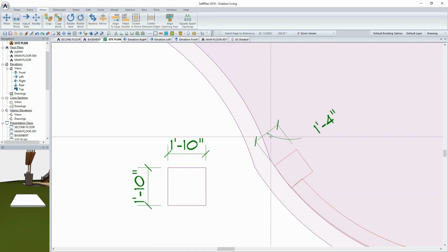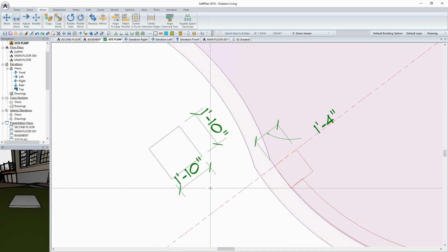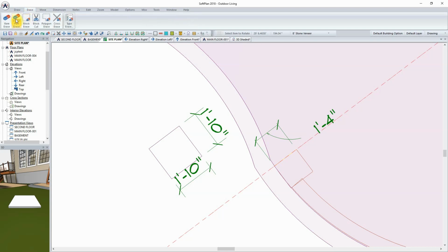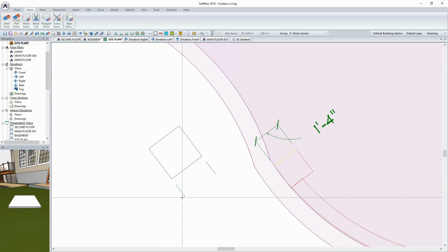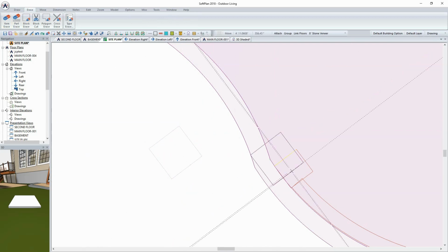And when I select this, I can pick this column, which is at an angle that really isn't measurable, so to speak, at 210.89 degrees, and then I can click the edge of the column I just drew and have it align that edge to be parallel. And so I'm just going to come in through item erase and remove these dimensions for right now, just to get them out of the way. And I can now move this on top of where the column is placed.